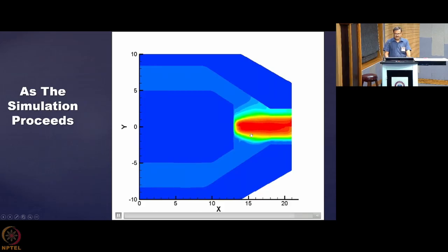But if I stop it over here, you see that the thermal equilibrium is much better. Earlier, we saw that the electron temperature was quite high in this zone, and the asymmetry between the heavy particle temperature distribution and the electron temperature distribution was significant. Now, here you can see that most of the zone is thermalized. So when you increase the diameter of a plasma torch, the device offers you a plasma jet which is more thermal.